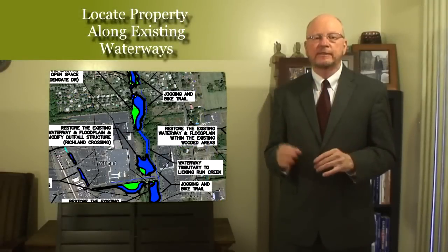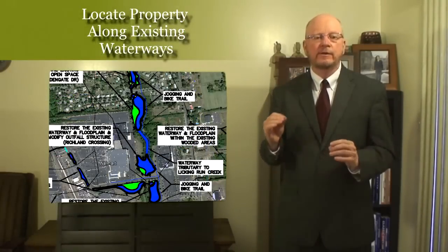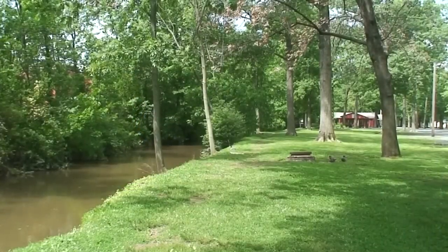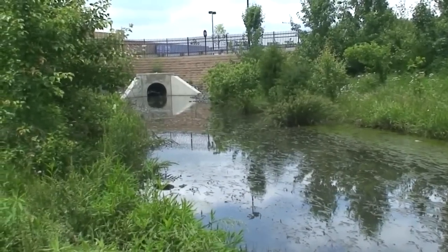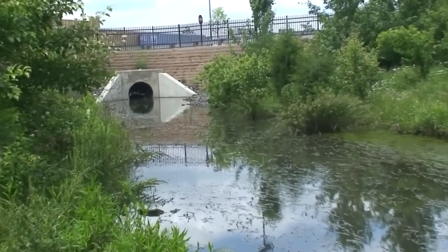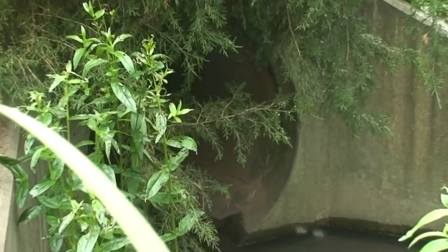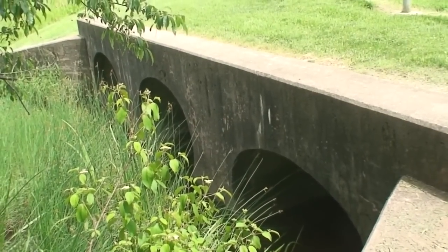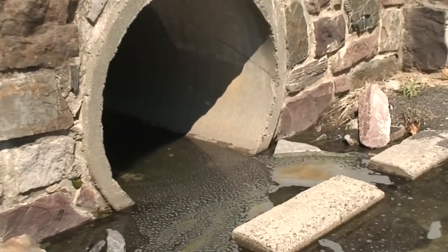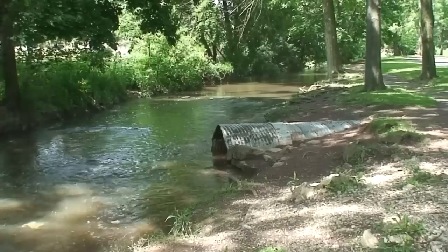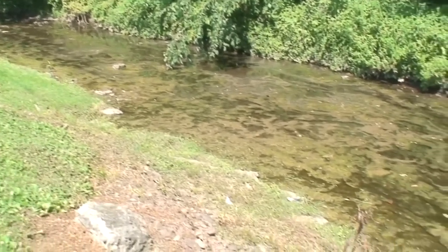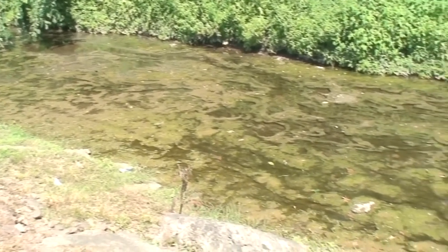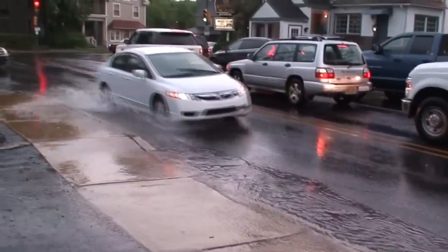The first step in this process was to determine where land or undeveloped open space were along the tributaries and find out who owns these properties. The property along waterway tributaries are where the outfall points are for all existing stormwater systems. In other words, this is where the drainage pipes from the existing built community comes in contact with the waterway that we want to improve. This location is where the storm pipes are draining into the waterway and is the most efficient place to construct stormwater runoff treatment ponds.